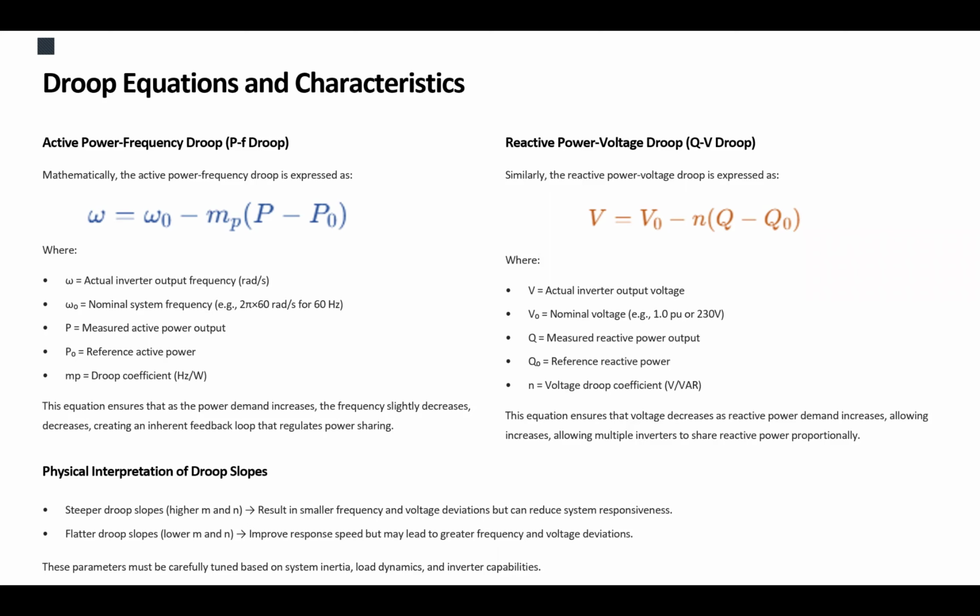There are actually several surveys run by different utility owners and federal agencies or governments in different countries that define a specific margin, so the manufacturer could have an initial setting. But eventually it's the utility owner's responsibility to model the system with that inverter and analyze how to set the settings and the amplitudes in the control system, so it could respond perfectly within the margin of the standard, without too much deviation or a long wait for the response to deviations.